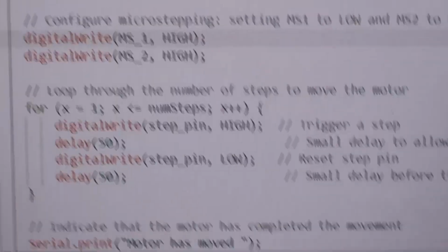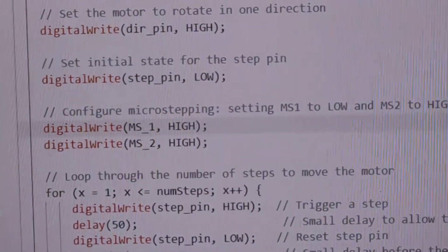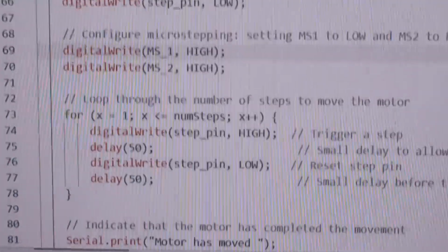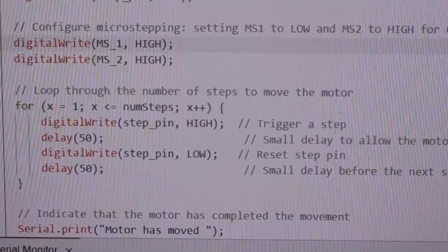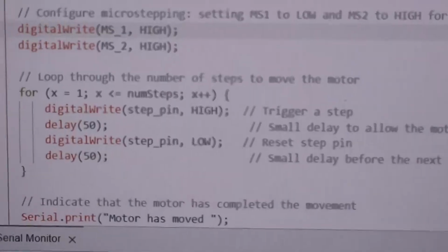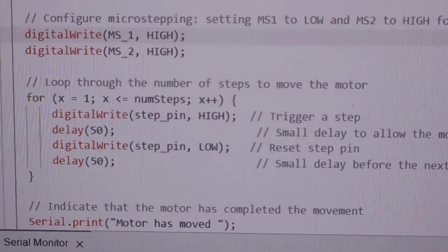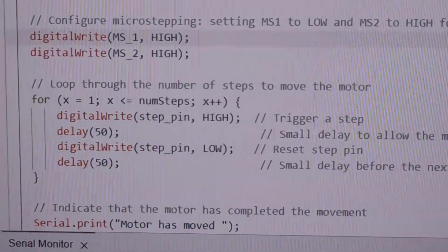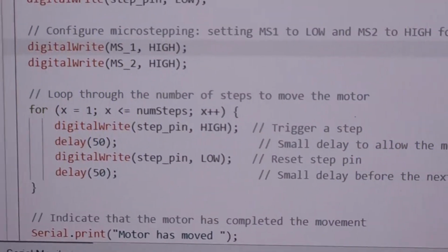So this is showing me that it is doing the different steps in different modes: full mode, half mode, quarter mode, and 1/8 mode. This is how we can change the step size for this stepper motor in full mode or in micro stepping mode. Now we can calculate how much it has moved. Let's now look at the different modes by which we can operate, as I had explained some time ago and also in the program.